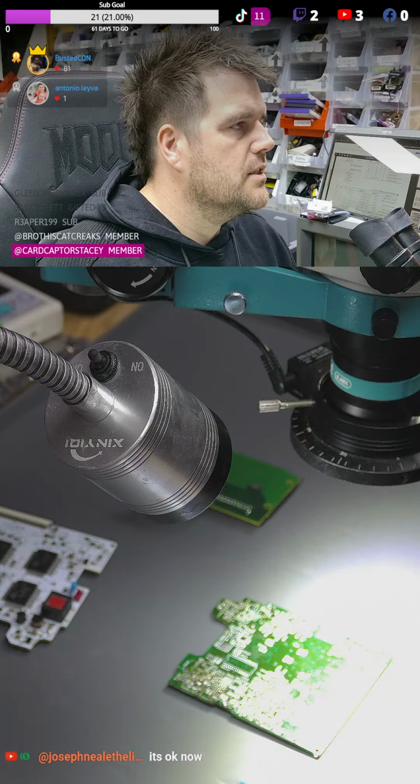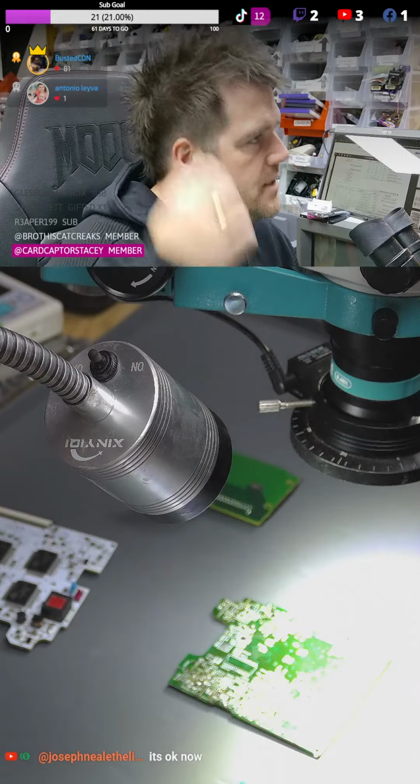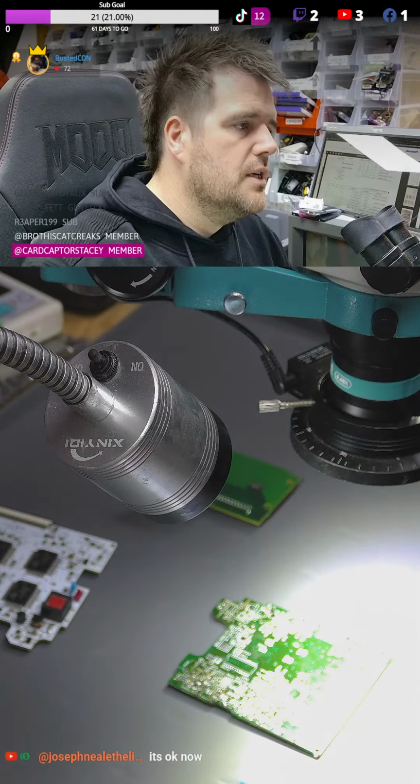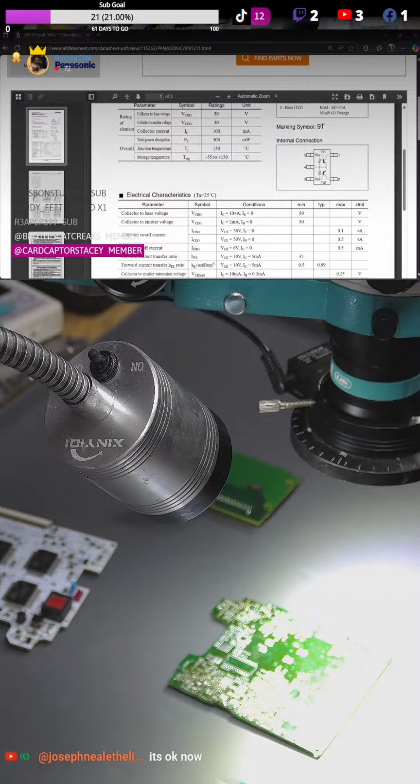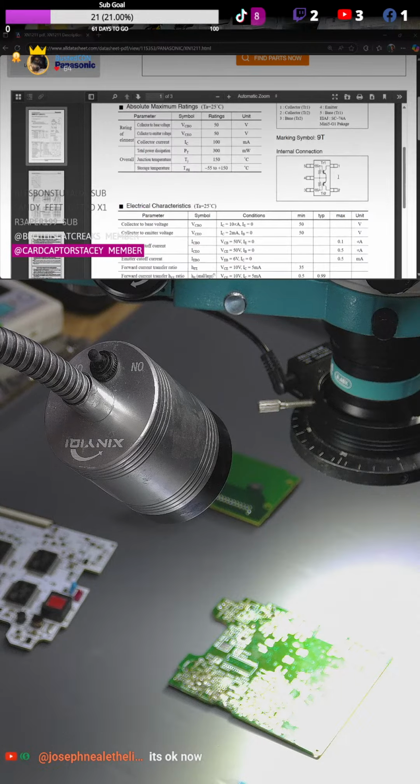Jump back onto this port. Well, we'll need that in a second. I'll leave that where it is. Bring the PC up over. So I think it's one of these, an epitaxial transistor. Not that common, but basically you've got two bases. I think these are NPN transistors. I can test that after. So two NPN transistors with two separate bases, but the bases are already pulled high and also available on pin 4. So you can control both the center tap point and the bases.